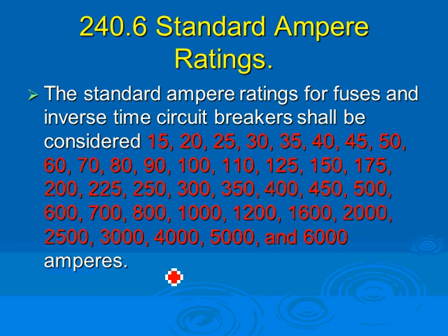So what they do is, here's my 6,000 amp bus, and in between, on the switchgear, they pull loads between every circuit breaker. Every generator comes in, and between every 2 generators they pull a load.